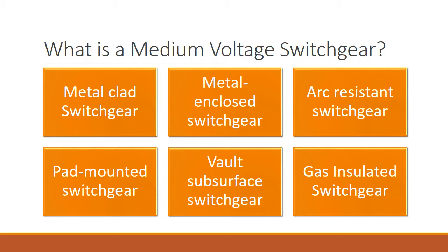And this is usually done by channeling arc flash energy via a plenum to a location where it may be discharged without endangering persons or equipment. Now, these specifications are defined in IEEE C37.20.7. If you want to learn more about arc flash in general, I do have an arc flash fundamentals course on Udemy as well.